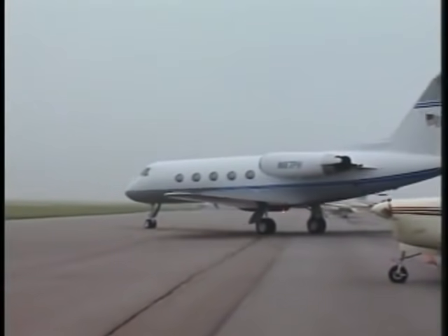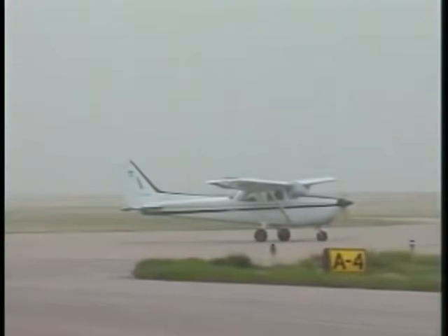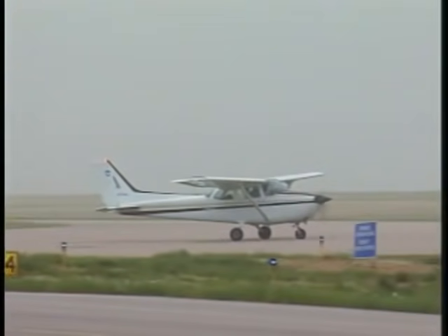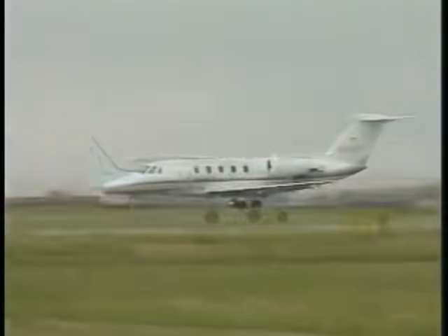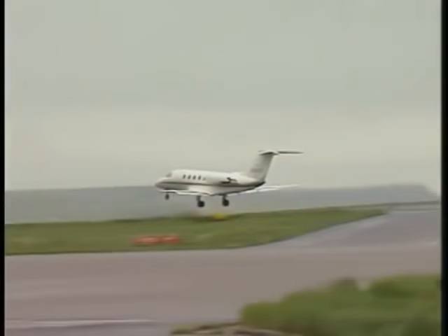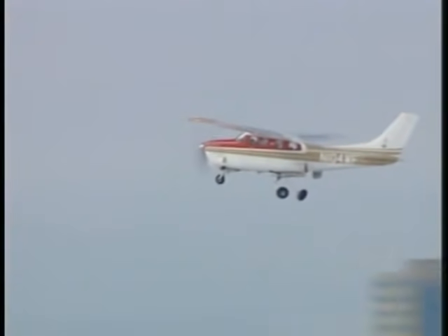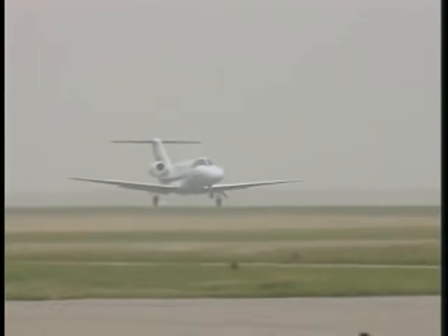Pilot nav and vector DPs have a number of advantages for IFR departures, including reduced workload for both pilots and controllers. Remember, all DPs make your climb out safer by providing an obstruction-clear flight path when you depart the airport. In the case of pilot nav DPs, vector DPs, and some textual DPs, this extends to your transition to the en route structure.